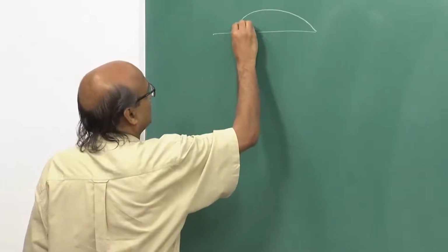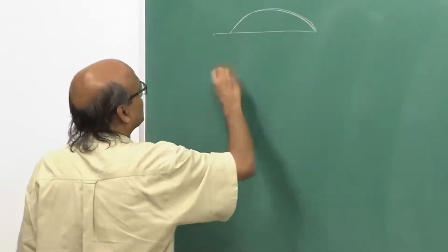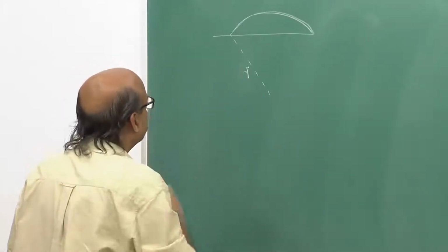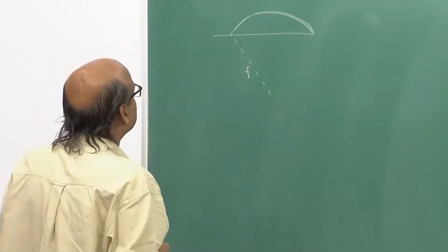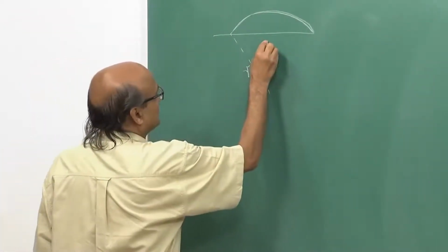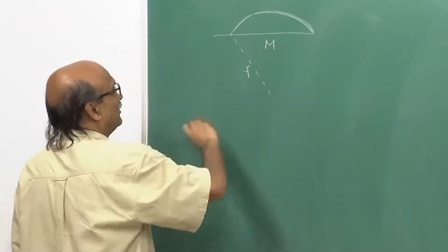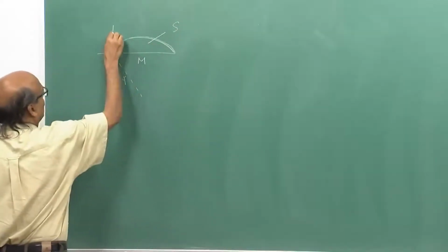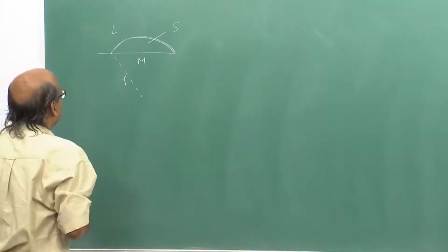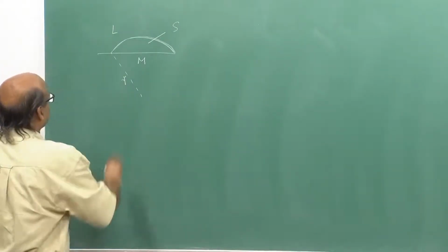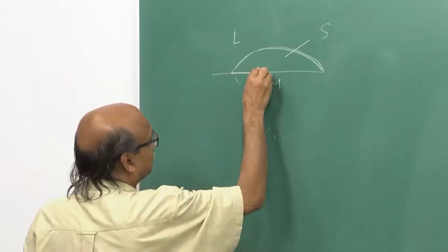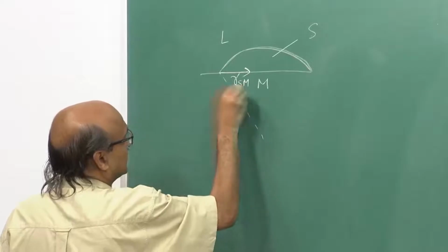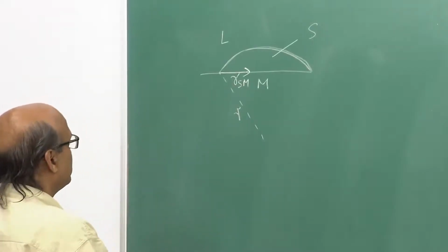So, this is my spherical cap of a certain radius r, and if I look at the surfaces involved here, this is my mold wall, this is the solid that forms, and out here is the liquid. As a result, the surfaces that are involved, there is a surface tension between the solid nucleus and the mold wall, gamma Sm.